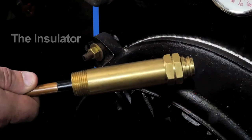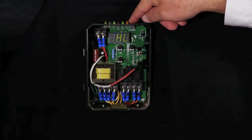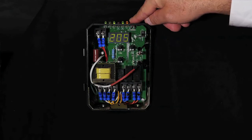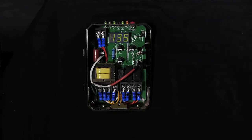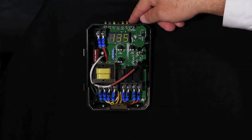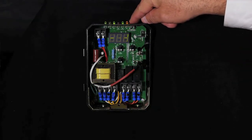To view current settings, press and release the test set button in short intervals to sequentially display the following settings. High limit setting will display as HL. Low limit setting is represented by LL. Economy setting is ECO, and the current target temperature will display in Fahrenheit or Celsius.